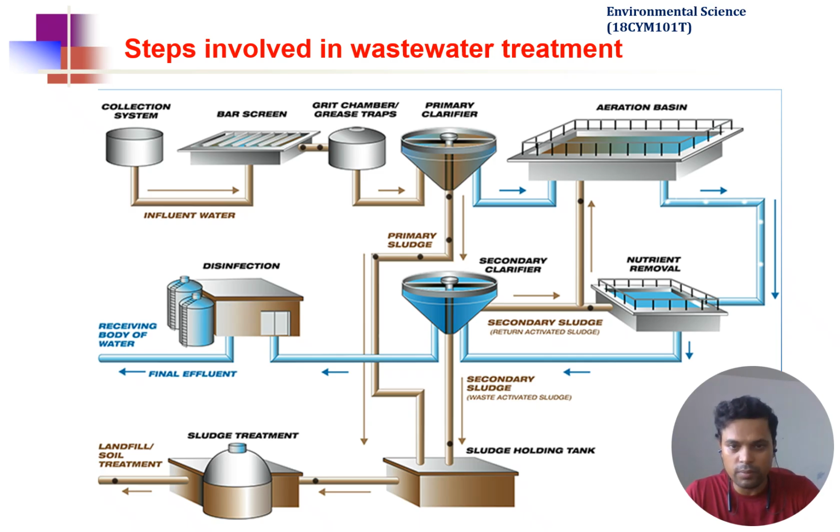And then from there we take out the clean water, and it comes to the nutrient removal plant, where the different salts, metal salts present, also known as TDS, will be removed. Another thing happening here is that we can bring down all this sludge. Sludge is basically all the bacteria, so that can be taken out from there.